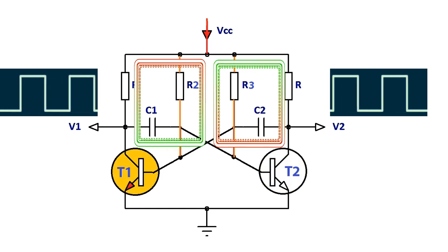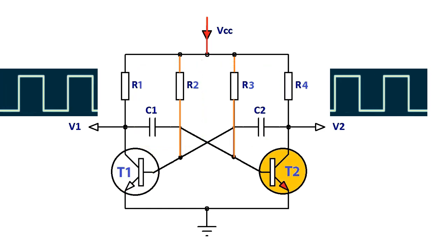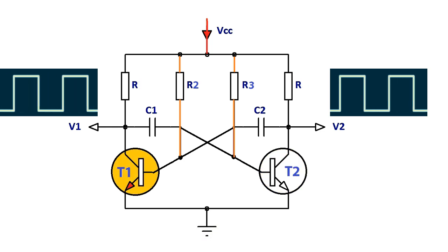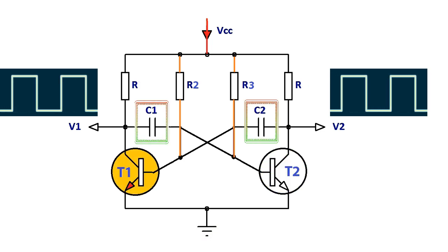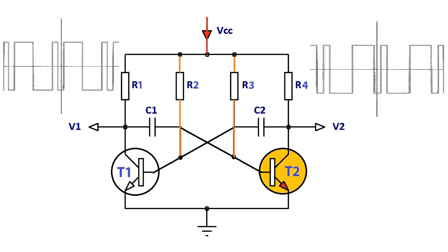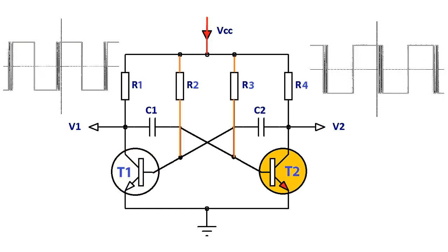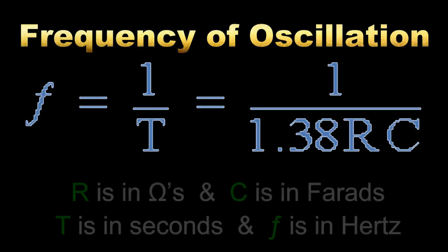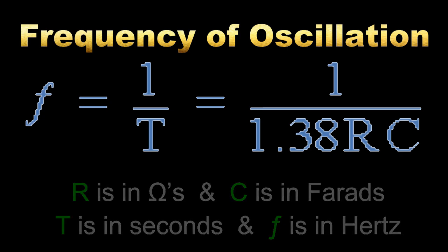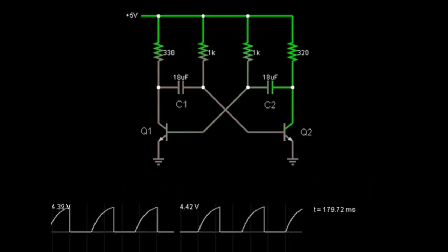If the two time constants produced by C2 x R2 and C1 x R3 in the base circuits are the same, the mark-to-space ratio will be equal to 1:1, making the output waveform symmetrical in shape. By varying the capacitors C1, C2 or the resistors R2, R3, the mark-to-space ratio and therefore the frequency can be altered. This is known as the pulse repetition frequency.